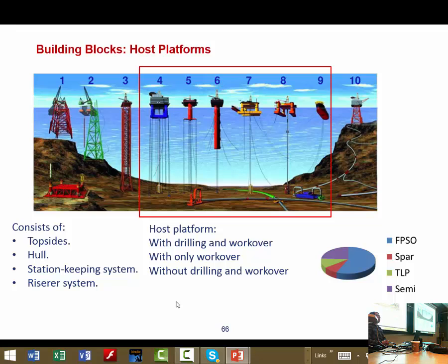Yes, please. In deep water or ultra deep water, the vertical movement, the height of the waves, are the same as in shallow water, or less? Actually, in deep water, because you have more severe waves, you should get larger vertical motions. But when you are in deep water, system is flexible in vertical direction because of type of the mooring system and riser type you select.